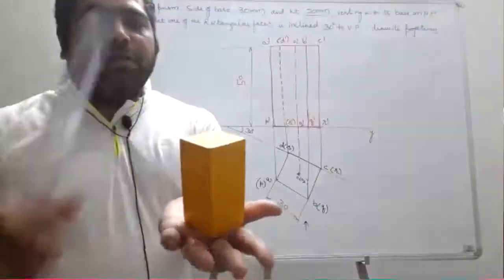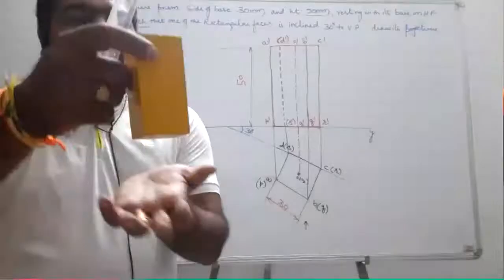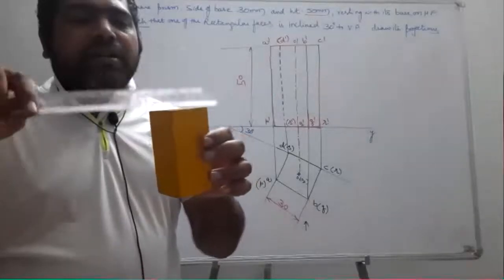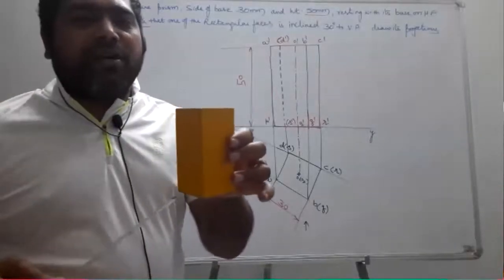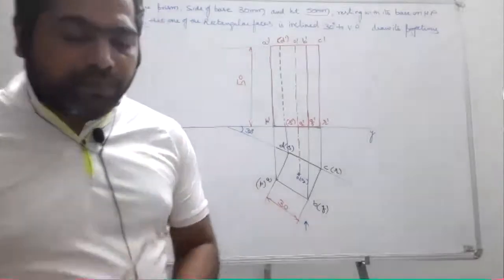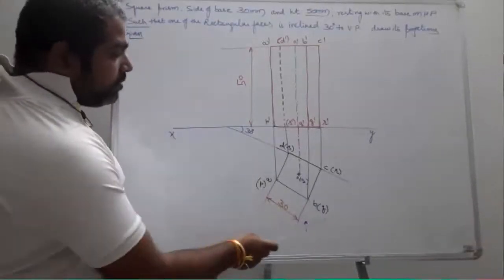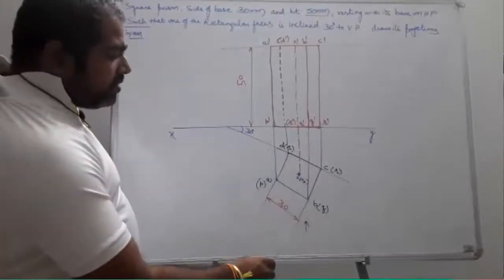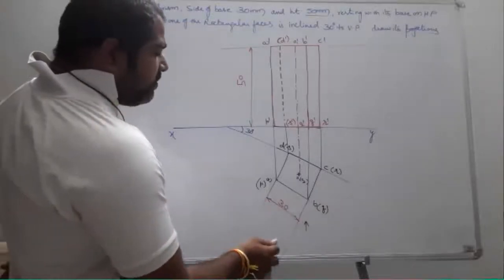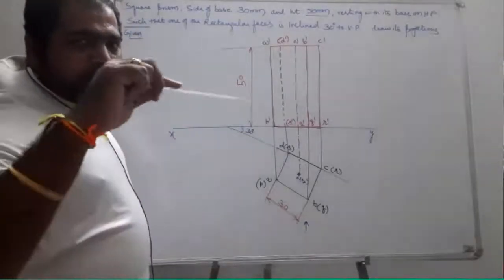Is it right? If it is going to be seen from the top, this square is noticed. It is ABCD, but the bottom is not noticed, but it exists, which coincides with all these corners. Okay, so these become the hidden corners. And the points are going to be PQRS in the bottom, ABCD in the top. So for that only ABCD are visible, PQRS are invisible. So while you are going to see from the front, okay, you are going to notice what are the points. A, B, C points are noticed, and D is invisible, in the top base.